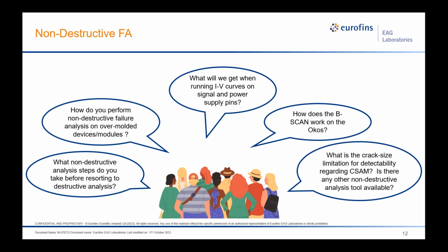As some of you might be familiar, the lower frequency transducers can penetrate very deep, but the spatial resolution isn't as good. The higher frequency ones have much better spatial resolution, but you can't get to the interface of interest because it's a little buried in your package or device. And so the XY footprint of the delaminated area is actually the most critical variable for being able to non-destructively detect it.